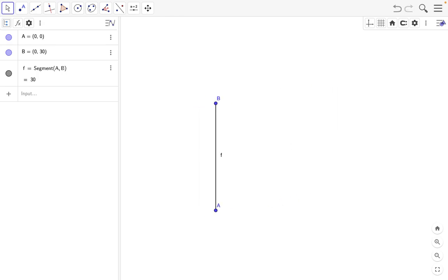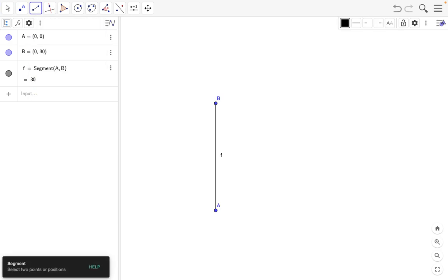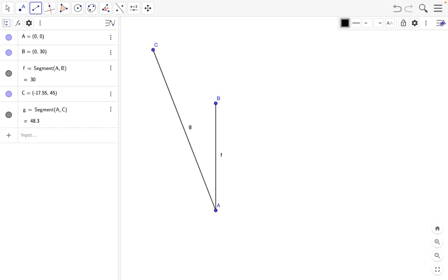Next, to divide this into equal number of divisions, say for example 7 divisions, what we will do, we will draw a line from this point of an arbitrary length forming an arbitrary angle, preferably an acute angle.